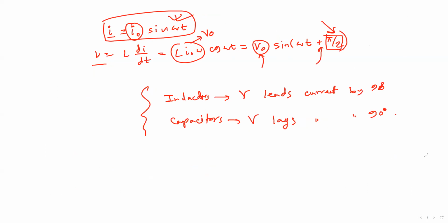We have already seen that i has this role that it rotates any number in the complex plane by 90 degrees. We can see similar ideas in case of inductors and capacitors also. So in case of inductors, voltage leads current by 90 degrees, as if you have voltage in the numerator and current in the denominator, then what you get is not a pure real number, but an imaginary number.